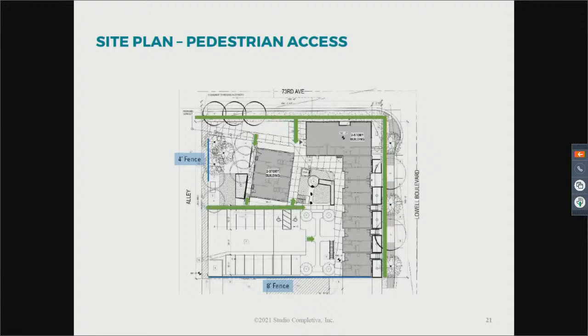Correct. So what we have not done is gotten rid of the right turn lane for the northbound portion. So when we look at resurfacing at a future CIP project or streets resurfacing project, we will look at restriping for the northbound. But this project will establish the parking on the west side of Lowell. Great.